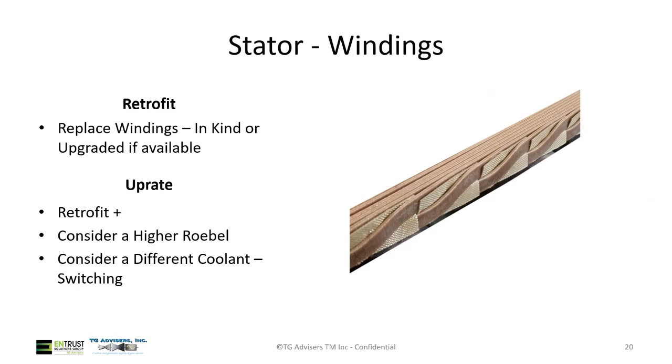Most of the time, it'll be in kind. Sometimes new technology has come along and they're upgraded by default. For an uprate, it'll be new windings with whatever new end winding structure that you have. Like I said, it's upgraded based on current technologies.